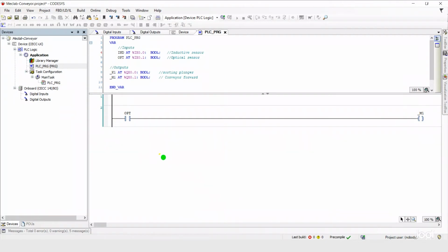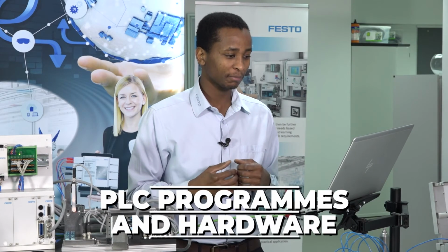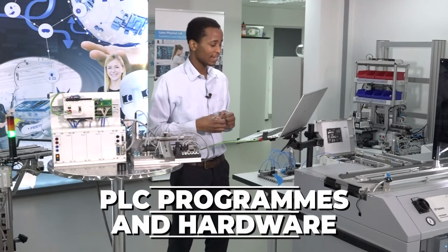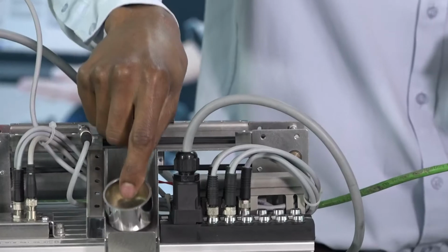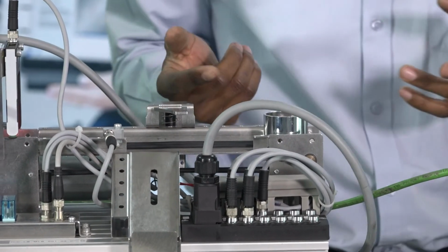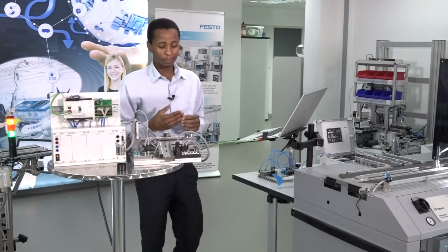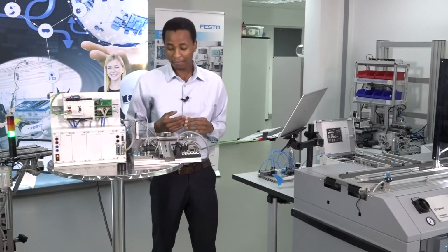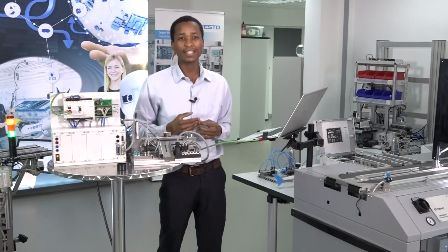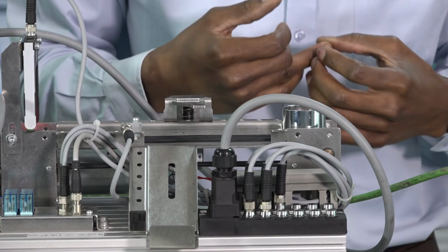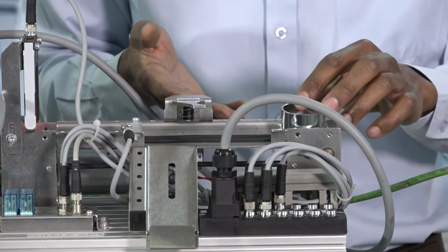Now, this will mean that the conveyor will run. However, immediately when optical turns off, conveyor will also turn off, and this is not what we want. We want the conveyor to remain running up until the material is transported all the way either into the slide or to the end of the conveyor. So for us to be able to have it running even after optical sensor has turned off, we use a function block, which you may be very well familiar with, which is a timer. T-off, which delays the off state of a variable, in this case the conveyor.